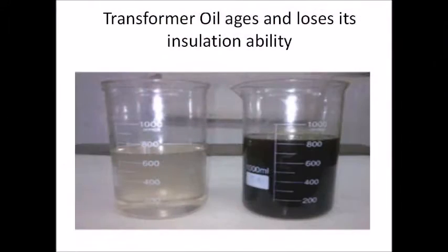These pressed woods are rich sources of moisture. And so is the cellulose paper. Is there any way of actually sensing within the transformer, like in the cellulose or the pressed wood, if there's moisture coming out of there? So far it has been very difficult, because the extent of the technology is that they have to sample the oil.